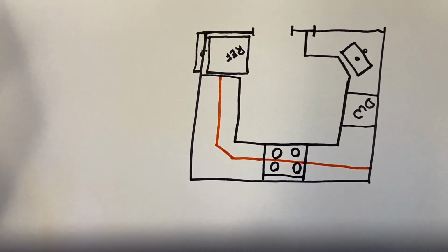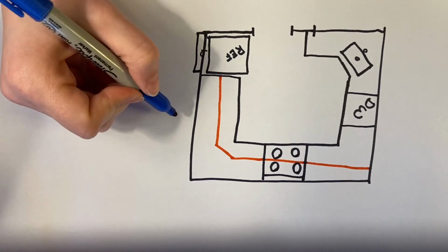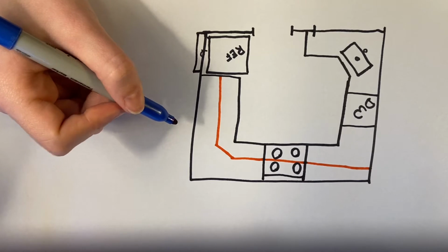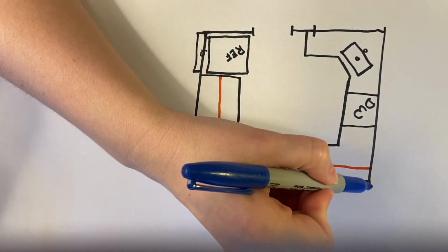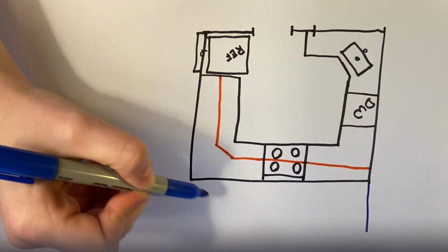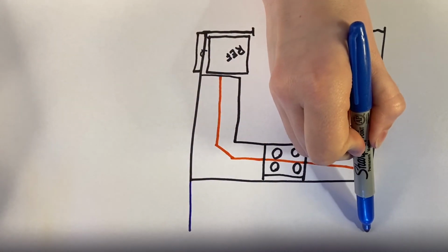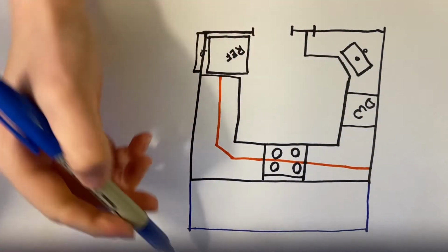So next up, we're going to start dimensioning. One of the things that I like to take into consideration is how this drawing is going to look overall. So when you want to start with your overall, you don't want to write that number super close to the wall, because the closer numbers to the wall are going to be your detail numbers. So to start, we'll do our overall of this back wall here. So I'll draw 2 lines from corner to corner up decently high,